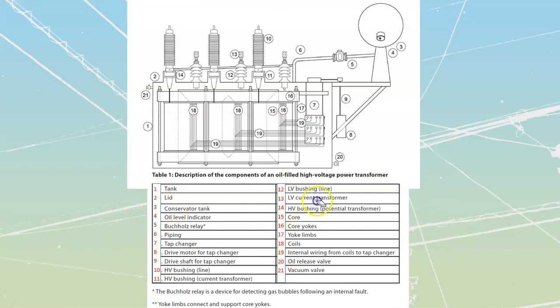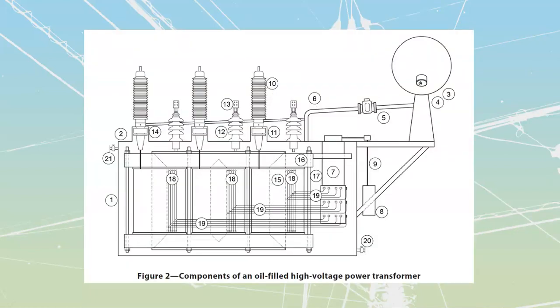All right, I'm going to go back to my bigger picture of the transformer over here. Tap changers are often going to be seen as a circular type of object because circular objects allow us to rotate through from one point to another. In second year, you should have seen some cutaway diagrams of tap changers. You might need to refer back to that. This is just going to be the same thing, but it's going to be covering 3 separate tap changes over here. And it's going to have our windings, which are carried from the inside of our transformer over here, carried out to these taps.